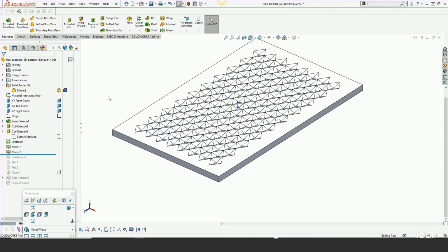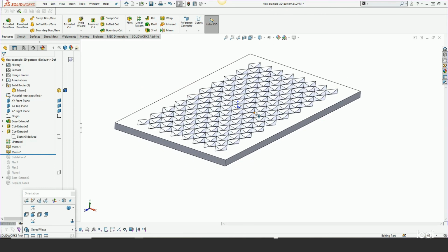And the design calls for, let's say this is like a knee pad, it's got to be deformed. It has to be kind of a bent radius, and that would be easy because you could maybe even circular pattern. But in this case, it's toroidal. It's bending in two directions, and those two directions' bend radiuses are different. So the approach I took here is, before I did these patternings, I figured out what does that toroid look like.